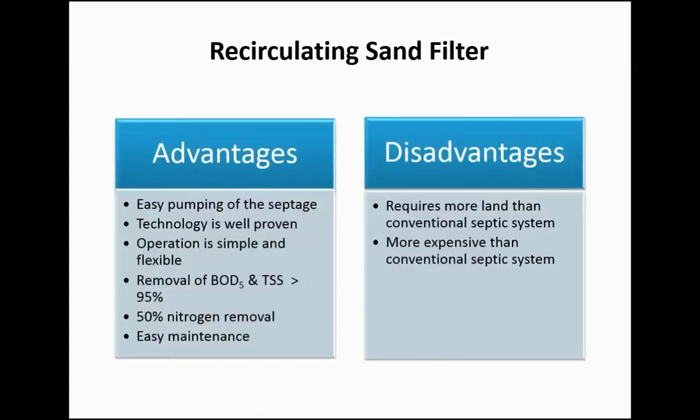The advantages are ease of pumping and maintenance, simplicity of operation, again 95% BOD and TSS removal, and 50% nitrogen removal. However, it requires a larger surface area, which is more expensive than a conventional system.